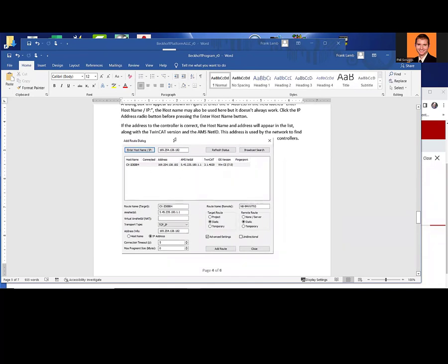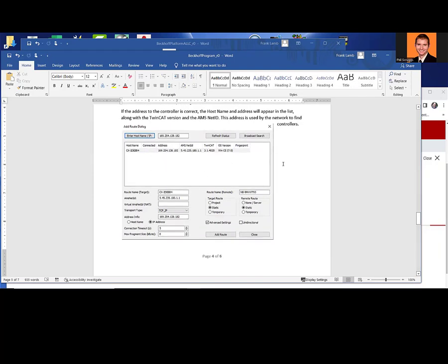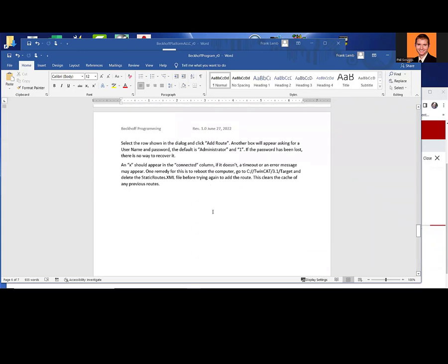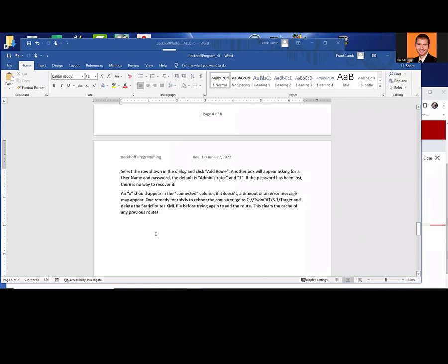I had a lot of problems getting this X. So this was the stuff that I had to connect to the guy up in Minnesota to ask him what the problem was. And we went through all the typical things, you know, you have the right mask and connection. And I said, well, yeah, because I pulled all this up and I got all this information from the controller, but it wouldn't say it was connected and it wouldn't establish the route. One of the things he told me that is nowhere in the documentation is he said, go in and delete this file. And this is not intuitive, right? Go into C:/TwinCAT 3.1 target, delete the static routes and add it again. And that cleared the cache and it did work the first time I did it.